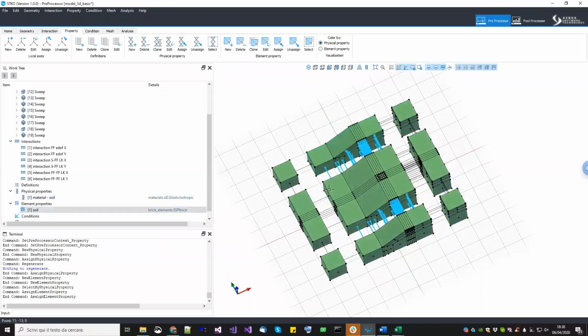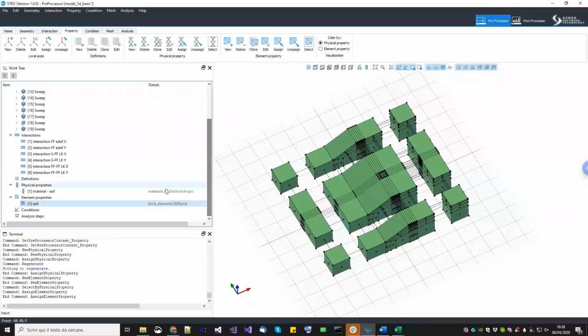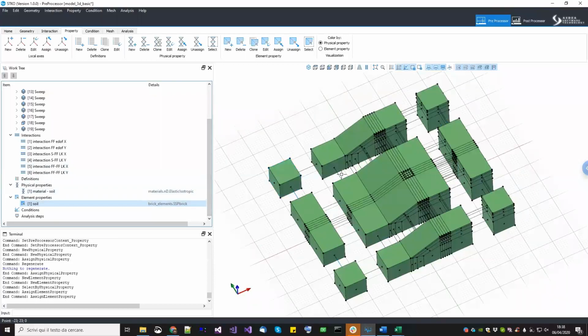Okay. So now the next step is to assign something to the Lysmer-Kuhlemeyer conditions. So let's go in physical properties. Now, the Lysmer-Kuhlemeyer condition, as you know, in OpenSees, they can be assigned using zero-length elements. So for a zero-length element, we need to create some zero-length materials. A zero-length material is just a collection of uniaxial materials in different directions. Okay, so we first need to create some uniaxial materials, and then we join them in a single zero-length material.